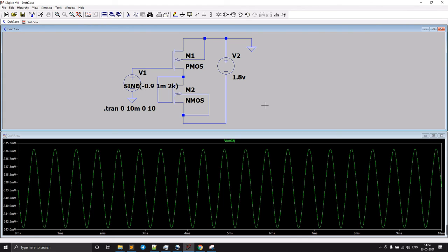In a more advanced circuit, we can increase the gain even more. So you can try with these circuits, cascaded with another NMOS or PMOS with the diode connected NMOS or PMOS. So even this circuit can be cascaded. I think you understood this. Thank you.